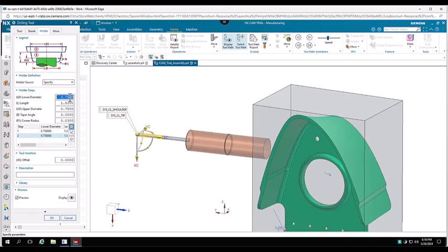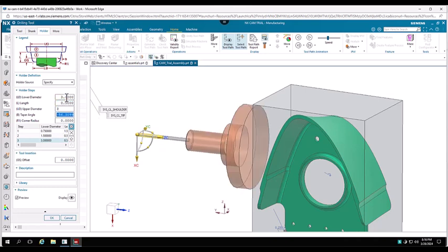So we want this to be a larger diameter. This holder is going to step out from here. So we'll make that 1.5 inches. Make the upper diameter 1.5 inches, and no corner radius, and we'll make the length 1/2 inch. So let's add another set here, and we'll just kind of mimic a flange of the holder. So we'll just say 3 inches, leave it at 1/2 inch, and do 3 inches again, and call that good.